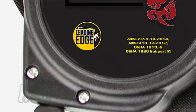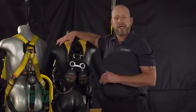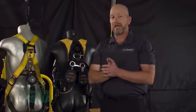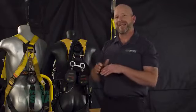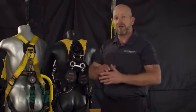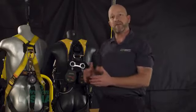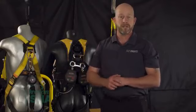There's a lot more to that. You should always investigate and assure again that we are using the right tool for the job. And just because you're working at an edge, whether it's an unprotected side edge or a leading edge, you have to concern yourselves with the fact that in the event of the fall, if the line can make contact with the edge during the progression of the fall, you must consider it a leading edge condition, thus having the right tool for the job versus one that could potentially shear.